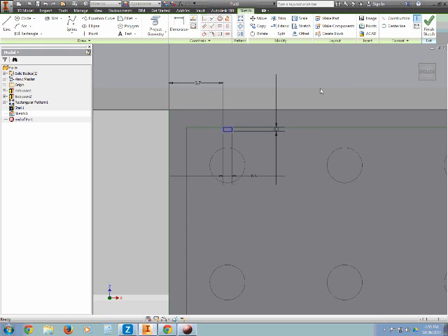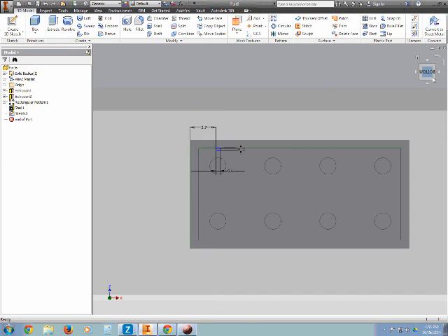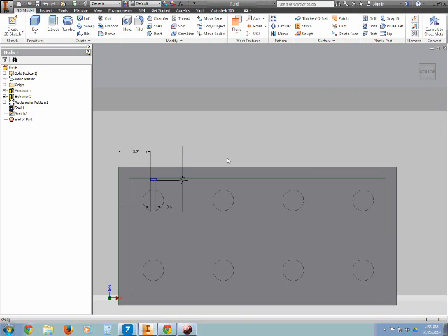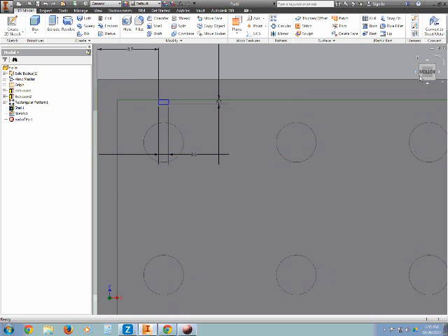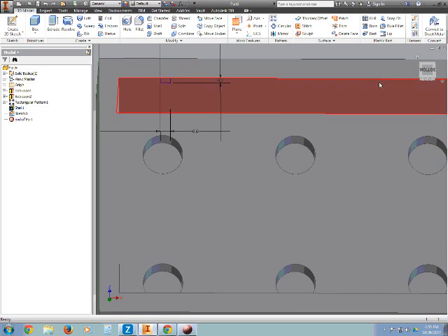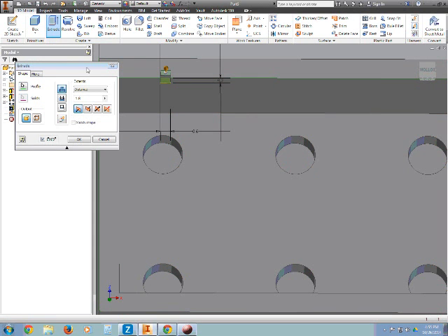So right-click and choose Finish Sketch, and we want to extrude this. Now this extrusion is a little bit different. I'm going to rotate it back a little bit. This extrusion is going to go from here to this surface. So we have to choose some different things. I'm going to choose the Extrude tool, and it's chosen my geometry for me, but I want it to go back into the screen, and I want it to go to the next surface.